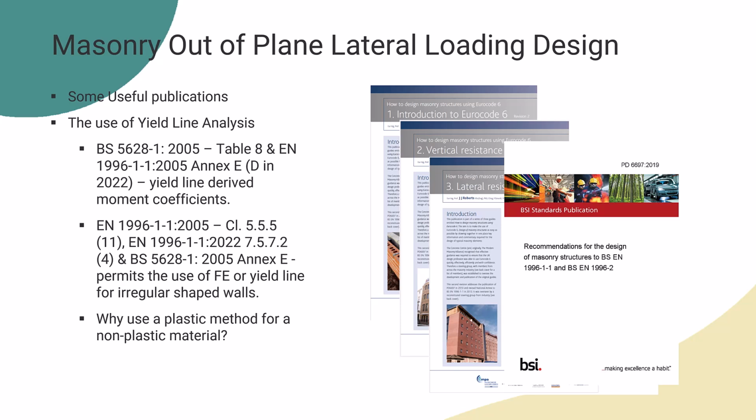Onto the topic then, specifically we're talking about out of plane lateral load design and the use of yield line analysis. Now, whether you know it or not, the approaches that the design codes take, both British Standard 5628 Part 1 2005 and the later Eurocodes, in addition to Eurocode 6 and Eurocode 6 2002, the very latest version, they all give us a method by which to design for lateral load based on bending moment coefficients. And these bending moment coefficients are actually derived from yield line analysis.